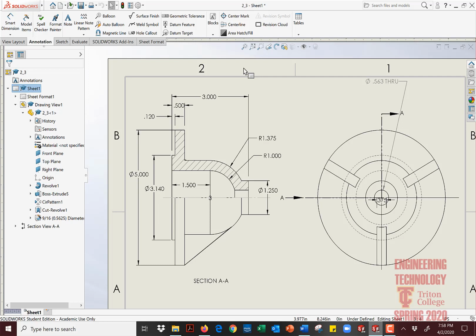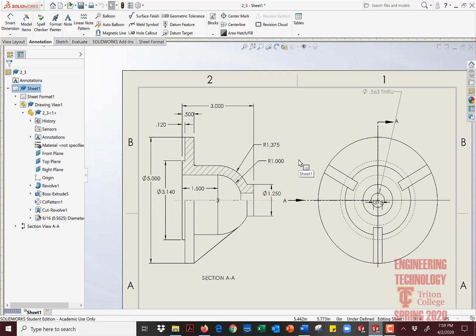And if they don't want tolerances this tight, or they're paying for tolerances that are not this tight, don't provide them with a drawing to approve with tolerances that are too high. Either it's going to be too expensive, or your company's going to eat the cost, and you never want to be eating cost, because then they won't have any money to pay anybody, including you. So be very, very attentive to this.